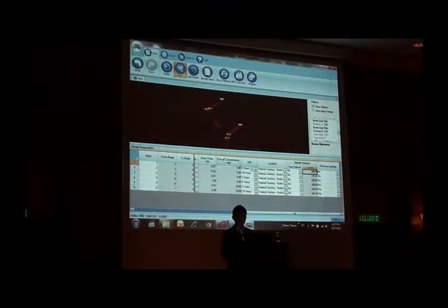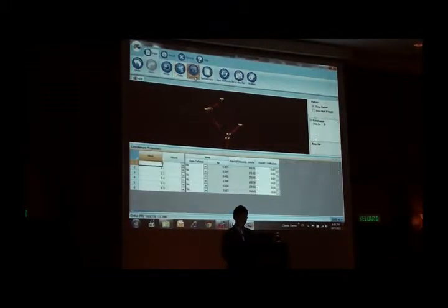After we key the data in, we can also choose user define yes, then we can key in our own value. For the catchment, it is already picked up from the drawing in hectare. The rainfall intensity is also done. Only the runoff coefficient we have to manually key in, or we can call out the chart.